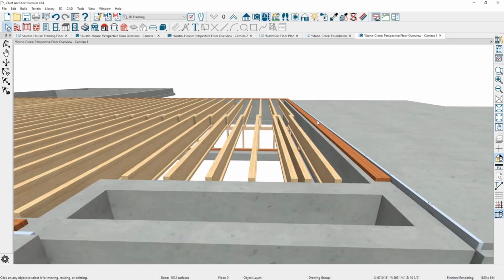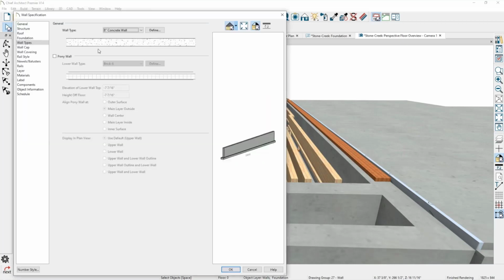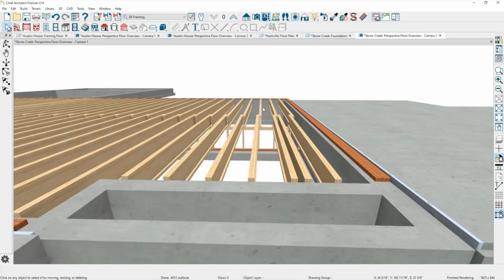Right. Yeah. I don't necessarily have time to go through and change all of this, but what I ended up doing is modifying the wall so that it's not hung, step one. So I would build the foundation so that these are not hung walls. I'd remove the check mark down here that says it's hung. Then those floor joists are stacked on top of the concrete wall. Effectively, that's going to raise this floor up on the left-hand side of the structure 15 inches.